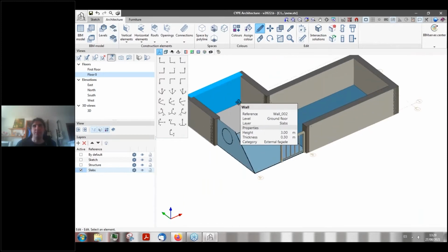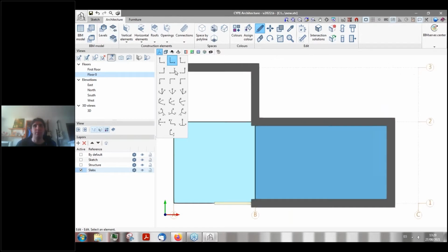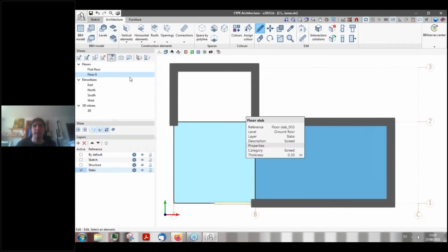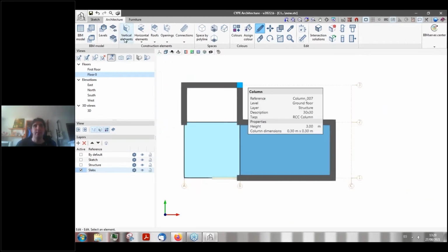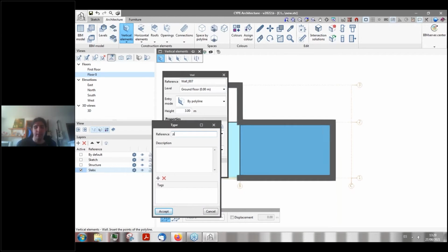Let's continue with the introduction of data. I'm going to switch here to this projection so we can switch to the floor plan as is. And let's insert, for example, a new kind of wall. For example, this is going to be a partition wall.